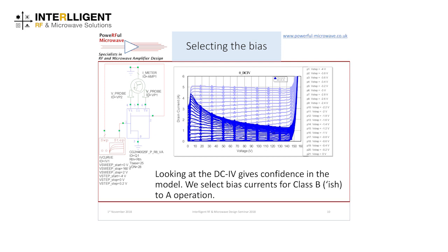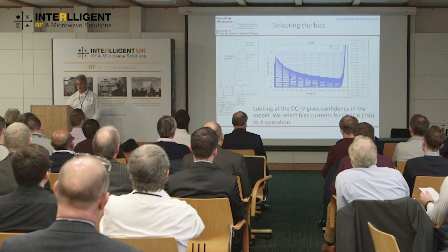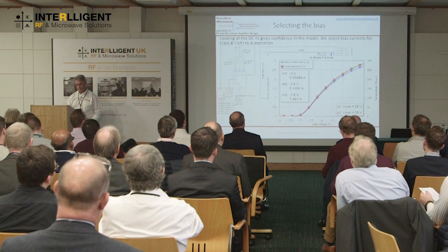That we're actually getting self-heating in the device, and that we've got the breakdown at around about 150 volts. So we can be quite happy, at least from the DC perspective, that this device is modeling the sort of effects that we would expect to see. It's got the signs of a good model.